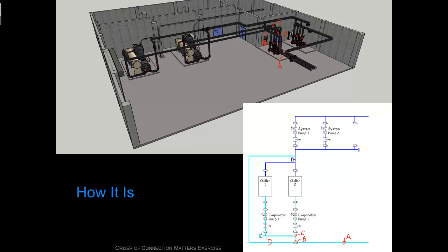And I come to the chiller specifically, the one that has no hot gas bypass and no VFD. So, here's this pipe, the service valves, the suction diffuser, the pump, the check valve, a couple more service valves. And this is the chiller, and since they're different, I'm just going to note that. It might be important to know. So there's no VFD, variable frequency drive, on that chiller. You come out of that chiller, you go through the service valve, and you come to another T.